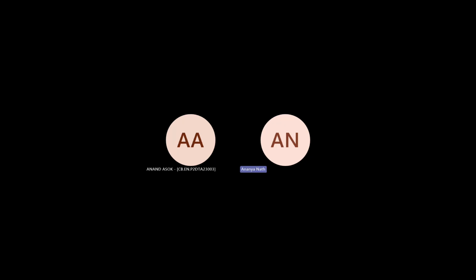Because when we print, we print layer by layer. So here we are talking about how the layers will be defined. In the previous lecture, if you remember, we talked about slicing and the STL file format. In STL, we save the triangulation of the whole surface, and then we cut planes out of it.